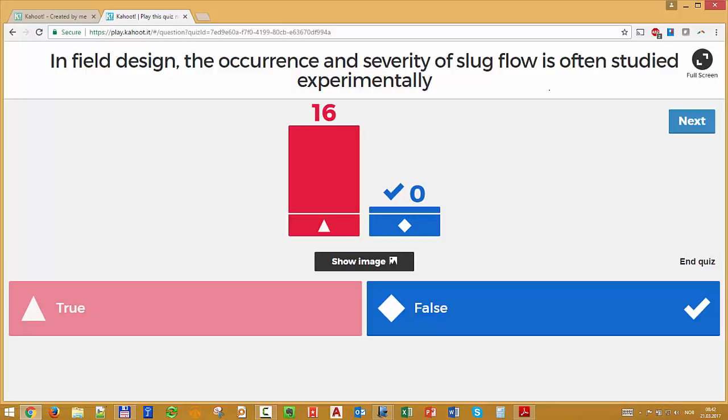That one I got you really bad. So that's also another trick question. Multi-phase flow experiments are relatively expensive to make, and you also want to make them in big pipe size, because the experiments done in 2 inch don't scale very well. Okay, 8 inch, 10 inch, but they are expensive. So really in field design, we usually use simulators. We use OLGA, LEDA, Flow Manager, to see if we will have slugging.